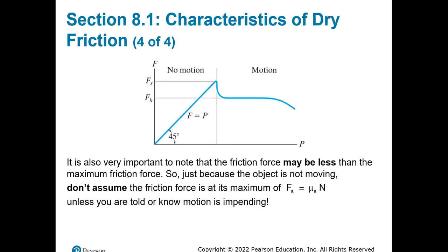It is also very important to know that the friction force might be less than the maximum friction force. So just because the object is not moving, don't assume that the frictional force is at its maximum, okay? Unless you're told or know that motion is impending.